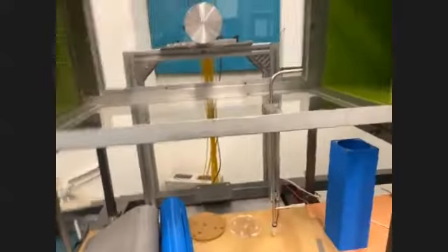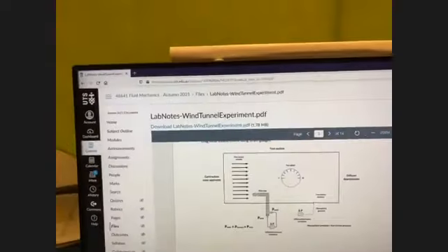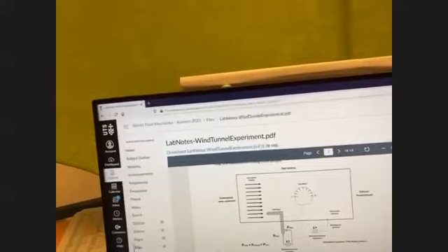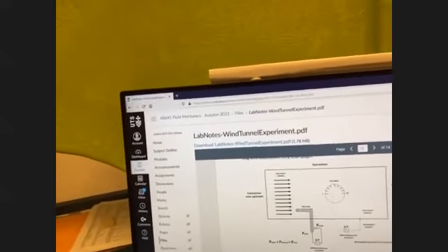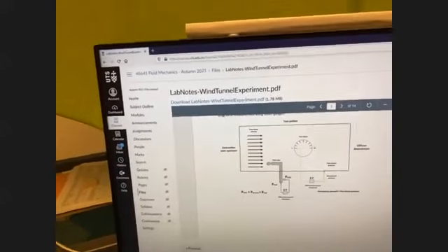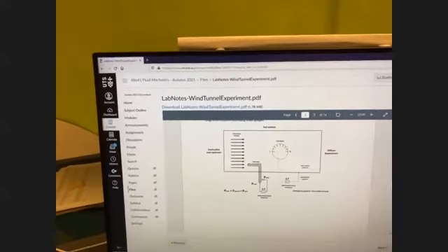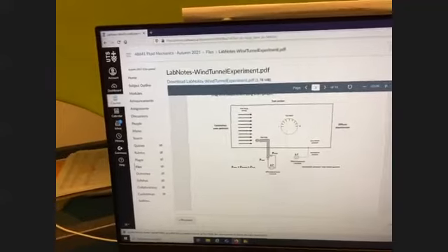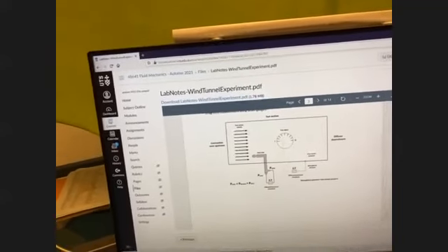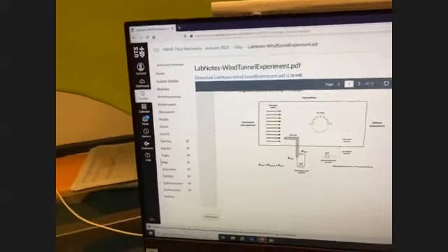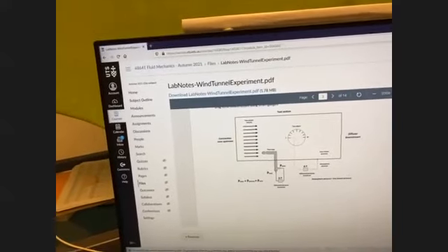On the other side, we have a transducer. Because this is fluid flow, in fluid statics we only have pressure depending on position. If we go up, pressure decreases; if we go down, pressure increases. However, in fluid flow, besides the static pressure, we have dynamic pressure, which depends on the moving fluid.